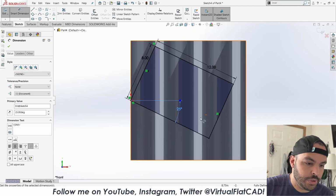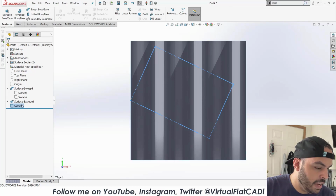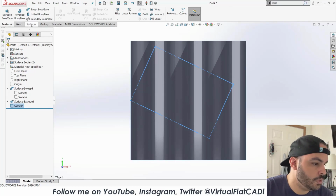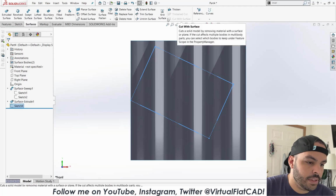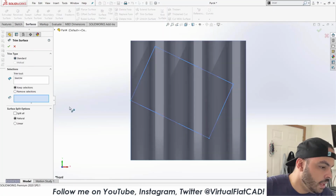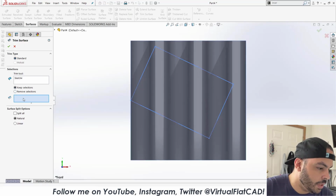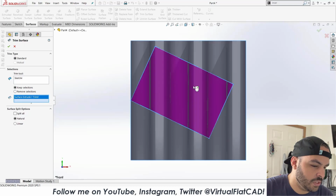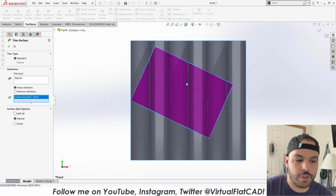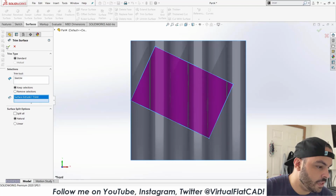25 degrees. Let's just try that out. So now I have my cookie cutter. All I have to do is go to surfaces and say, let's do trim surface. And since we're trimming with a sketch, you can leave it on standard. We can say keep selections. It's not too much of a difference if you say remove and you click the outside here, but we'll have something like that.